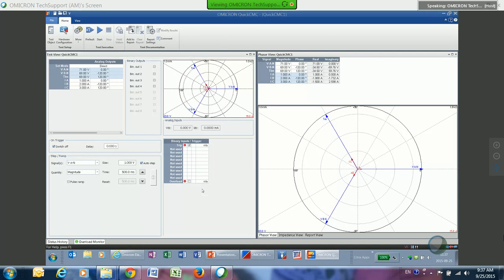So you have a trip command here, or a trip input, and you've got from 1 to 10 binary inputs here, but I'm not using the other 9. And then also at the bottom, I have an overload condition. If I overload that circuit, basically I want to trigger that one maybe to turn it off. So I can check that box, and it's going to now turn my test set off based upon an overload condition.